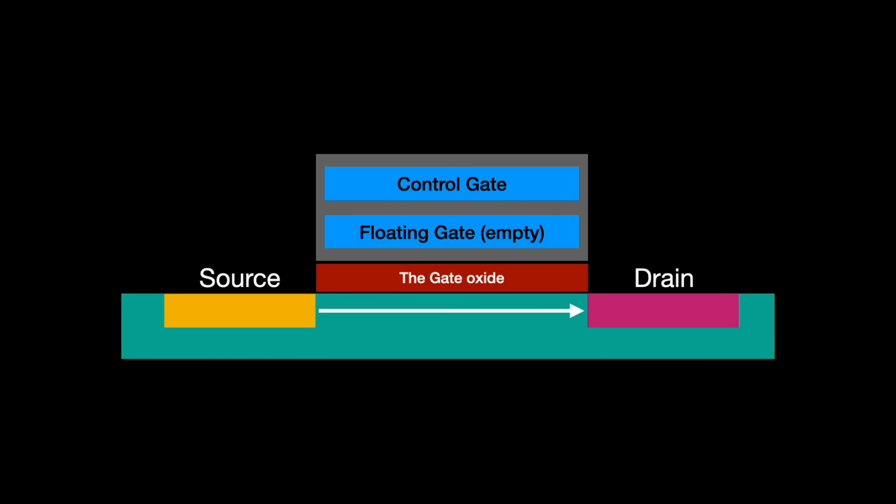This is done with a twist. In an ordinary floating gate transistor, called a single-level cell, the cell only has to map 2 distinct states, and that's because a bit has just 2 combinations, 1 or 0. To have that cell store 2 bits, we need the cell to somehow show 4 unique combinations, 00, 01, 10, and 11. This is done by grouping the charge level into 4 threshold voltage groupings.